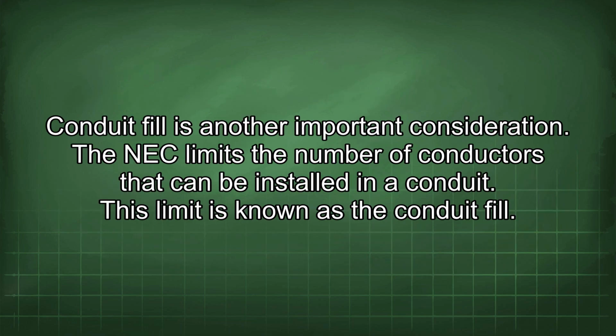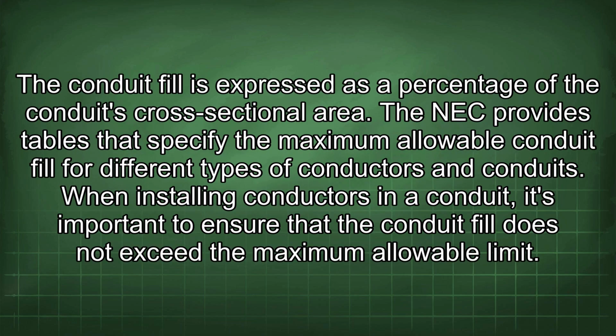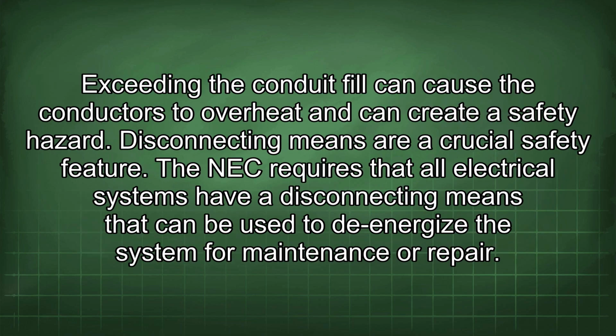Conduit fill is another important consideration. The NEC limits the number of conductors that can be installed in a conduit. This limit is known as the conduit fill. The conduit fill is expressed as a percentage of the conduit's cross-sectional area. The NEC provides tables that specify the maximum allowable conduit fill for different types of conductors and conduits. When installing conductors in a conduit, it's important to ensure that the conduit fill does not exceed the maximum allowable limit. Exceeding the conduit fill can cause the conductors to overheat and can create a safety hazard.